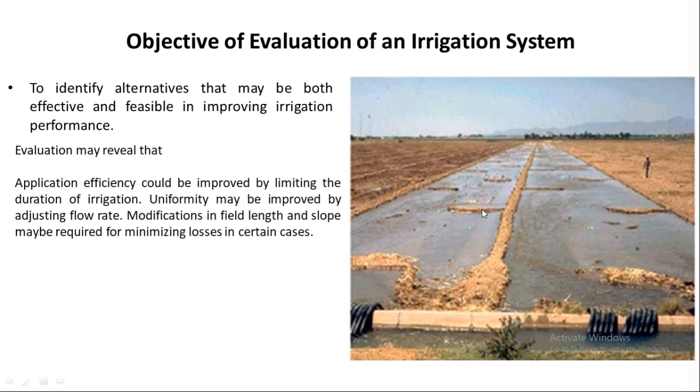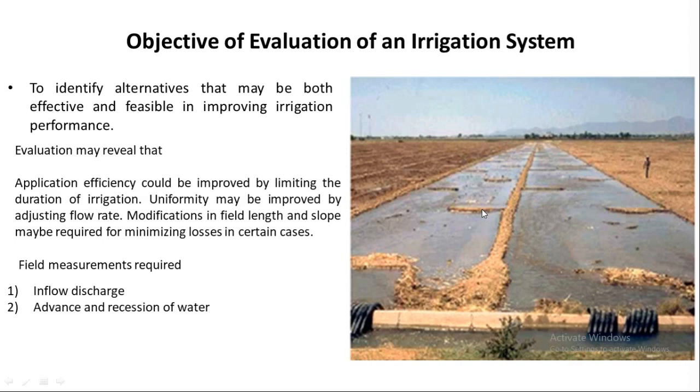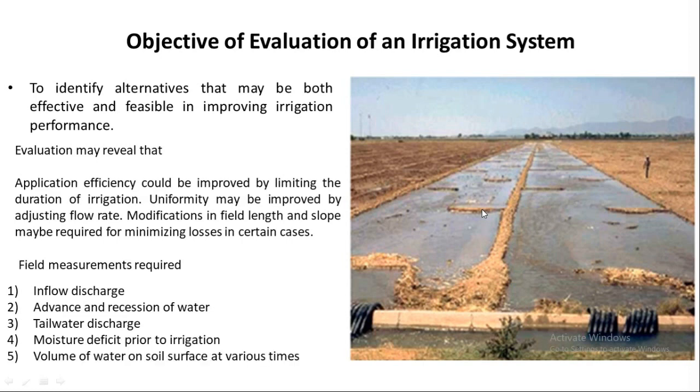And for a thorough evaluation, we need certain measurements like inflow discharge, advance and recession of water, tailwater discharge, moisture deficit prior to irrigation, volume of water on soil surface at various times, and indication of infiltration characteristics.